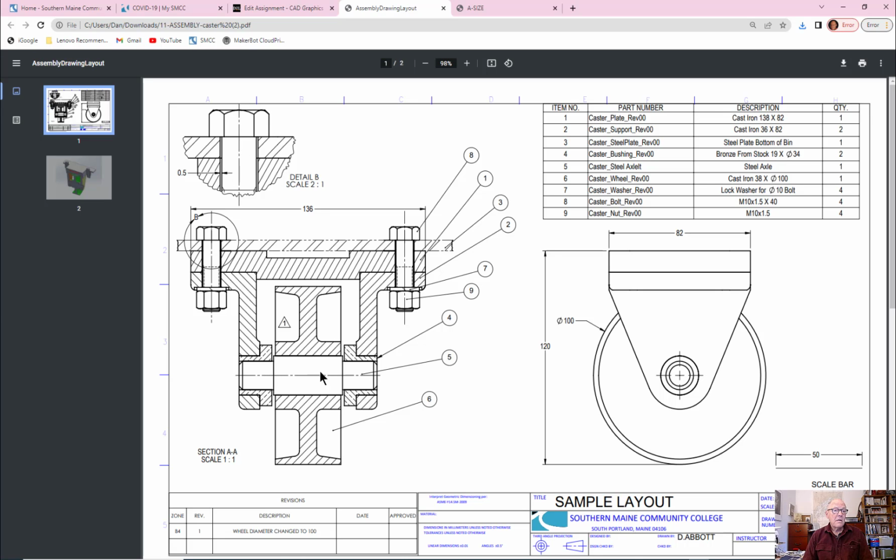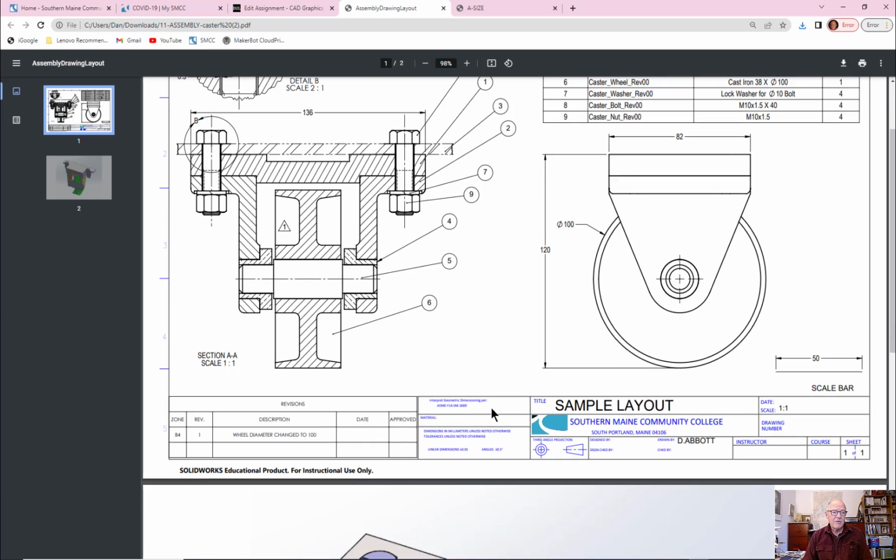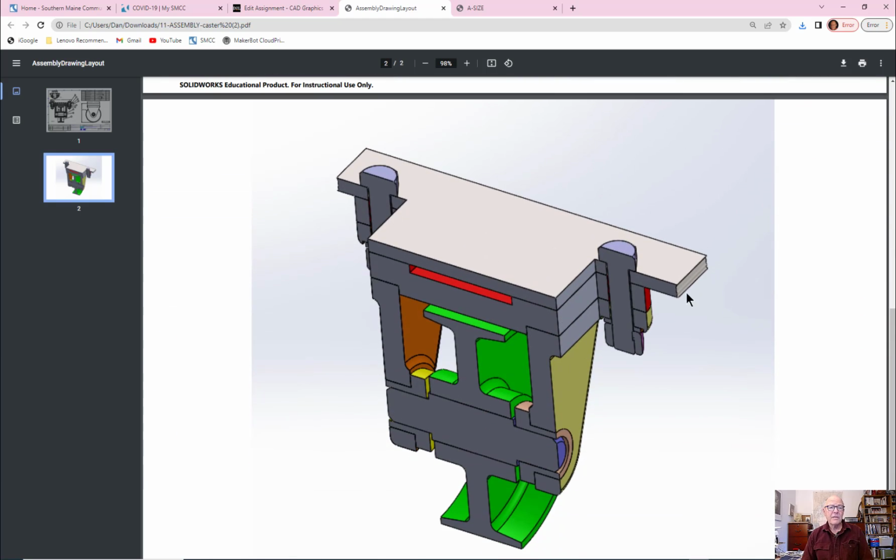PDF file. Now if you want to just visualize what I'm talking about, this is the assembly put together in SolidWorks. Now this is not what it would look like in the drawing, but this is the idea conceptually that you're going to cut offset through the assembly. So you're starting a cut that goes right through the fastener, offsets over to the center of the entire assembly, offsets back, goes through a fastener. So the individual components, you're going to show that surface, that surface right there, that surface right there. You're not going to include those edges because they don't really exist, so it's just what the edges would be if you were able to cut this.